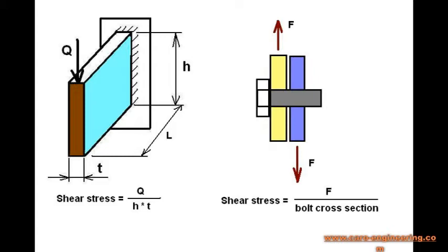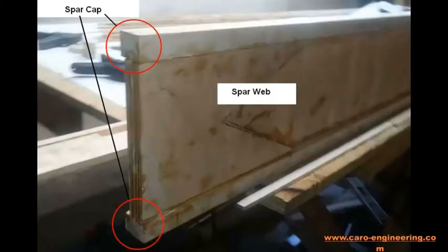of the beam. This is also used in the second example, where a bolt is subjected to shear between two plates. But this only works if the length L is short or the thickness of the plates with a bolt is small. A spar is usually very long compared to its height, so the spar web between the caps is experiencing shear stress in a different way.